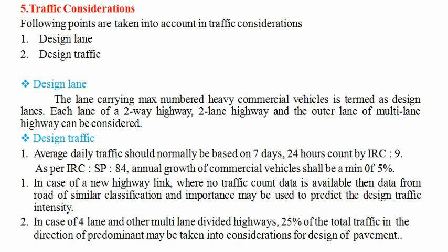Next is the traffic consideration. The following points are to be taken into account: first is the design lane, and second is the design traffic. For the design lane, the lane carrying the maximum number of heavy commercial vehicles is termed the design lane, and each lane of a two-lane highway and the outer lane of a multi-lane highway are considered.